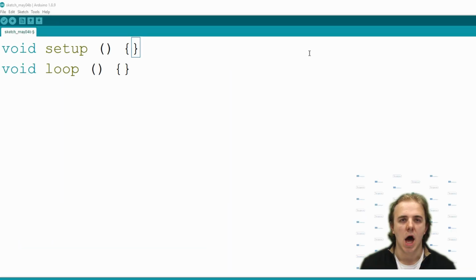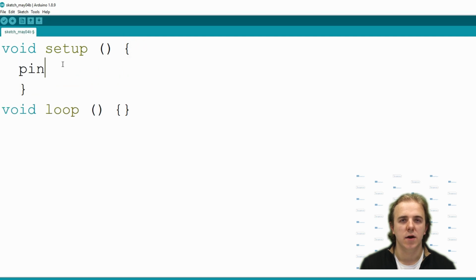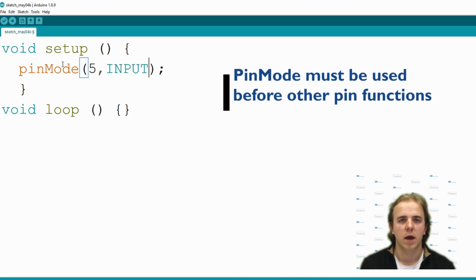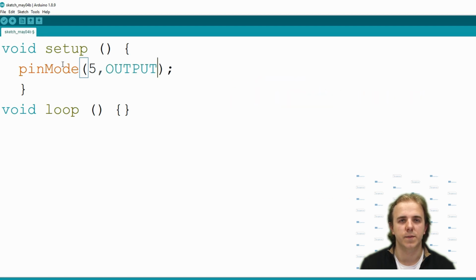In this video, we will talk about Arduino general purpose input-output pins and learn to use them with hardware. Arduino pins can be configured either as an output pin for controlling devices and sending information, or as an input for reading sensors or receiving information. This configuration is done by using the pin mode function. The function has two parameters, pin number and functionality, either input or output.